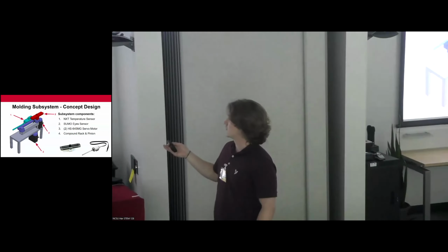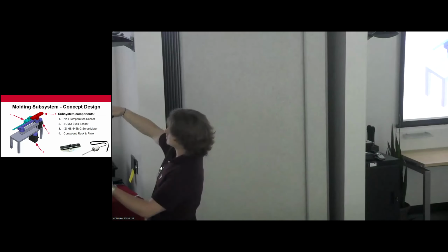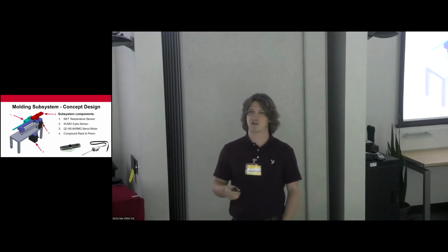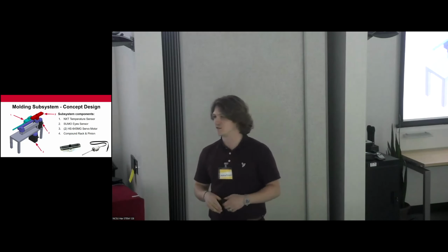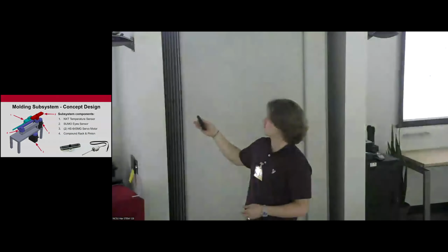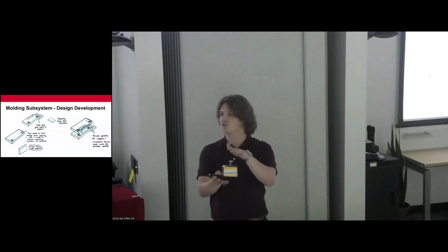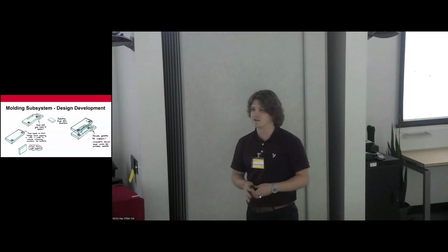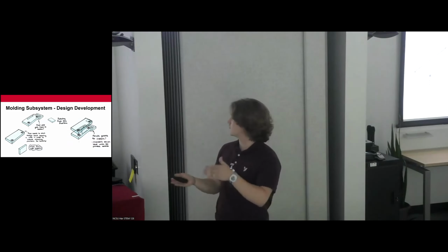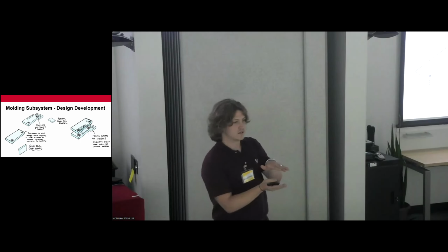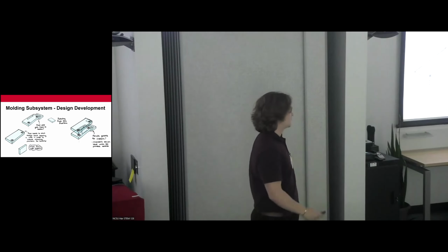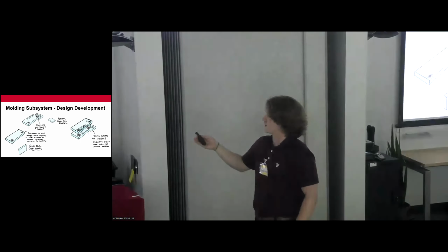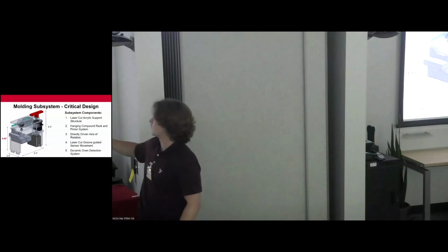Moving on from concept, right about this time, as you can see, the arm up top with the sensors on it is very crudely just sitting up there on the pole at the moment. At this point, we had no idea how that stuff would actually sit up there. So we needed to go back to the drawing board following concept design and create something that could hold all of these different sensors in this compound rack and pinion gear we had come up with, because without something to hold it, it's not going to do its job. We came up with this sandwich of acrylic plates that could hold each of these components up there. After a little bit of tweaking, I think we built this thing 3 or 4 times, eventually we got it to where it was consistent and did what it needed to do, and that is how we got to our critical design, where everything here is going to be laser cut from acrylic.